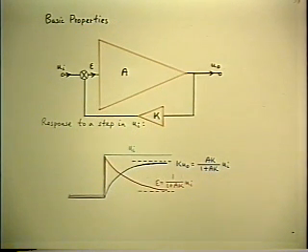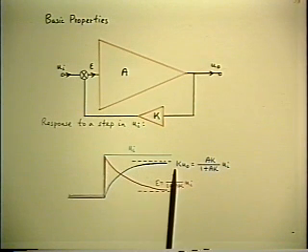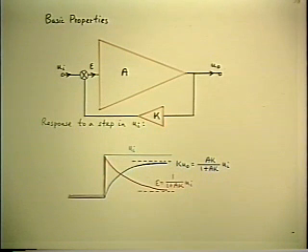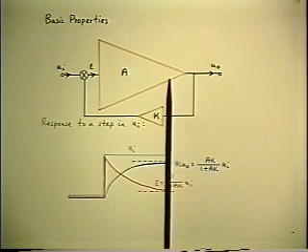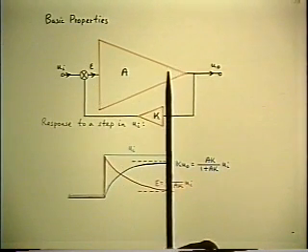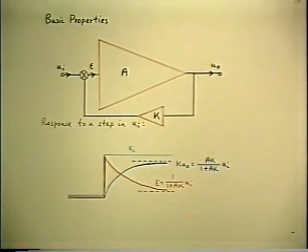One thing is for certain about it, it'll take a lot longer to reach the final steady state than if the system had remained linear. So that's something to watch out for, especially with modern ICs that have all this gain. It's very nice to have all the gain, but it's also very easy to overload them.